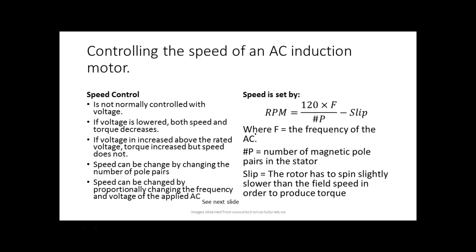If you've got a ceiling fan, it's usually a 3-speed fan. You go over and you click it. What are you doing every time you click it? Changing the number of poles. You're not changing Alabama Power's 60 cycle, because I can't change Alabama Power's frequency, right? So Alabama Power runs a frequency of what? 60 hertz. In fact, our whole continent uses 60 cycles, all the way up through Canada and all the way down through South America.